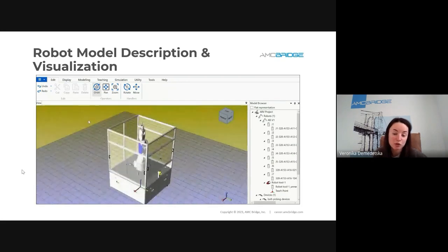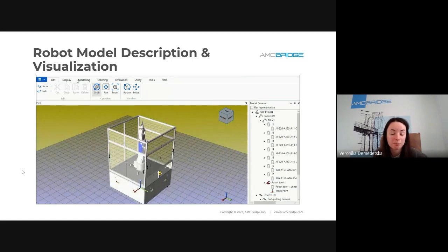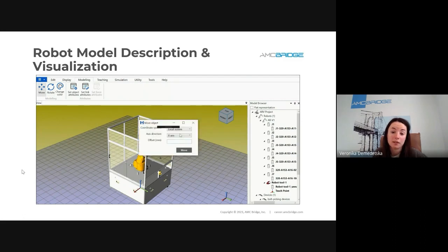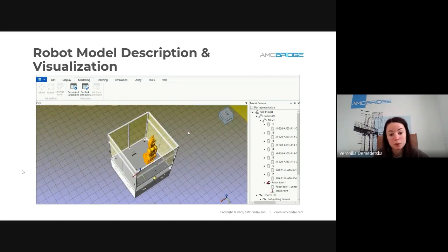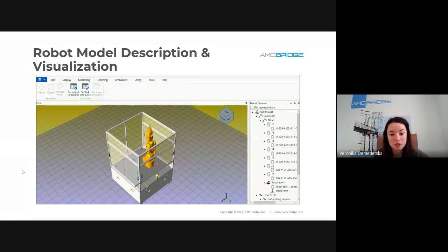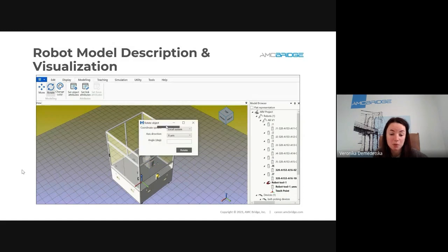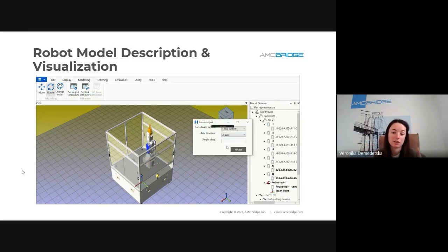So here we used, for example, Hoops Visualize 3D rendering engine to be able to parse the project file in that URDF format and load the geometry for the scene, for the device, for the robot surrounding, and for the robot itself, of course. So what we can do is to describe the robot, visualize that, and set up every player in the right place on the scene.